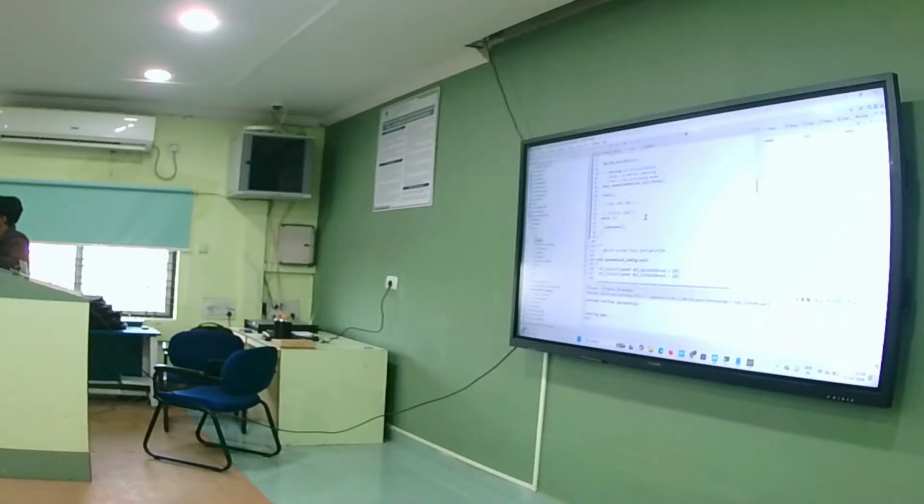Try to understand the code, which is very simple. Three functions I added there: void train, void inference, then void fill buffer. First I created a for loop of length of the axes number, not buffer size of 256. Then I added each and every sensor sample to that for loop. Then that sensor sample I take for training the data. First I train the model.